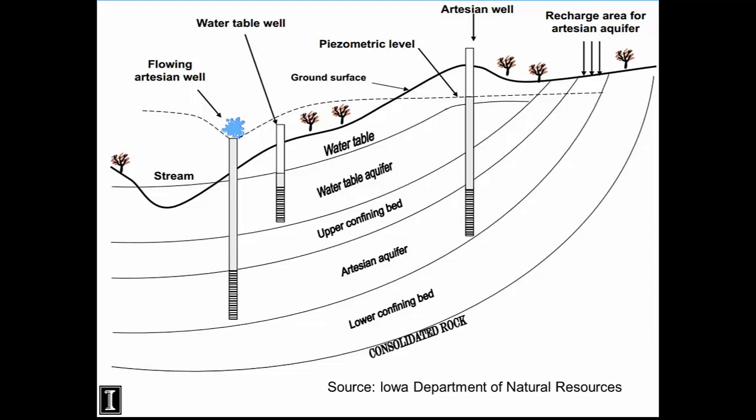They're angled. And so, for instance, in the Chicago area, they use a deep sandstone for their water supply. A lot of communities do. And the sandstone's as much as 1,800 feet below land surface. That sandstone comes to the surface about 100 miles west of Chicago because it's on this angle. And that's the recharge area for that aquifer.